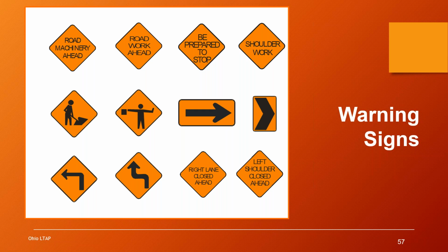So you'd actually have 4 signs in advance of your flagger, and this would be the third sign in your series. That's talked about in typical application number 10 in the options. It's been proven to make your work zone safer on those high-speed 2-lane rural roads.